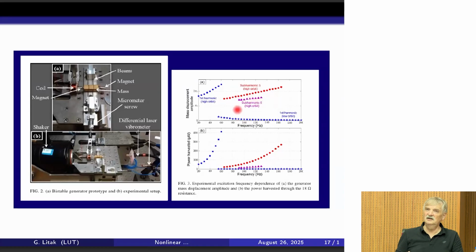So it was interesting. If you look at the power output, the lower figure is the power output in correspondence to the amplitude. You have a larger response in amplitude. You have also voltage output, which is proportional because this is linear. The electrical system is linear, however here this is power output. So this is voltage squared. If you have relatively small voltage, then it is unfortunately even smaller, but if you have relatively large voltage, then this is even higher. So it is such a tendency.